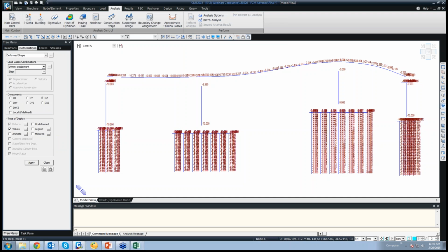If this is not done, then even for the self-weight load case, the bending moment would be considered showing the 10 mm settlement. Now that won't be right, because we add the moments. We use the principle of superposition. So the self-weight moment would be acting as it is. Besides that, if there is a 10 mm settlement, then what happens? To check that, we have to create a load combination with self-weight and 10 mm settlement. That would give us the resultant moments.